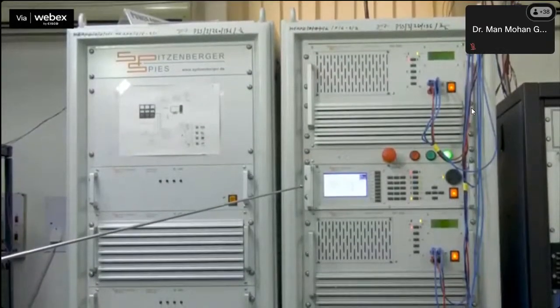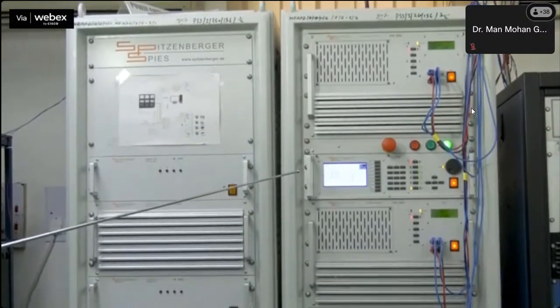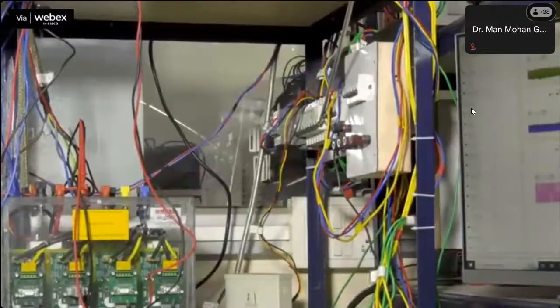While the stator of the slip ring induction motor is connected to the power amplifier via a switch, the switch is initially open and is further closed when the stator voltage and phase angle are synchronized with the voltage and phase angle of the grid using the rotor side converter.